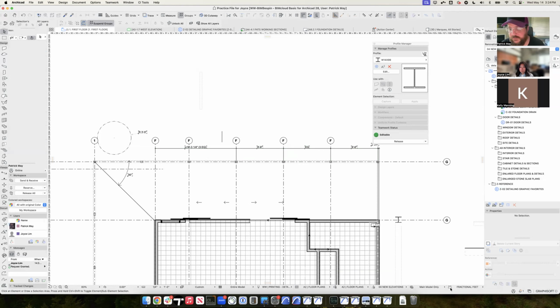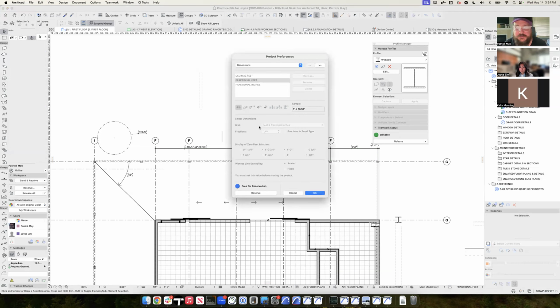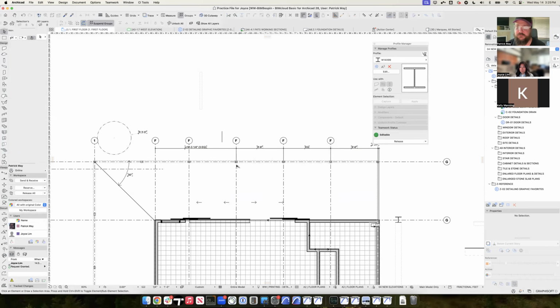The other thing about the dimension is our dimension styles. If we look under the view settings here, our dimension styles are dimensioning to the nearest 64th of an inch. And that's intentional. That is there so that if our model is off at all, we correct the model and it raises red flags so that we don't end up with cases where the total dimension string says 44 9 and a quarter, but maybe this says 16 foot 3 and 3/8.